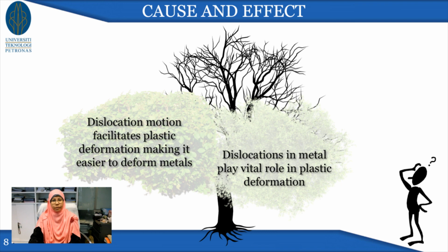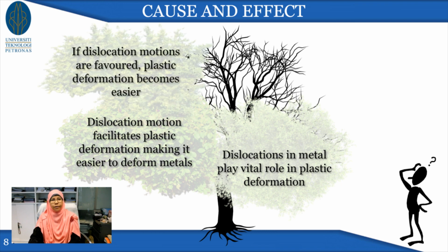If dislocation motions are favored, and you make them happen easily, plastic deformation becomes easier. With nothing to block the motion, a little force will easily deform the material.